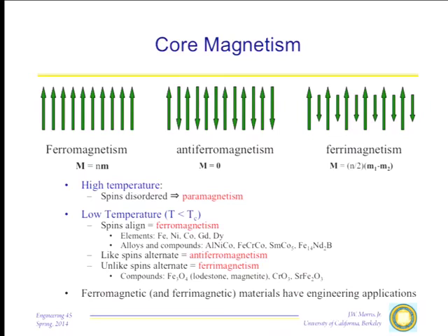It's also the case, when we get to more complicated materials, that there are a number of compounds that become ferromagnetic, even though the elements are not. Gosh, if you were a bit older, you would have used tape for recording music, and the best tape was chromium oxide. Chromium is antiferromagnetic, not a very good recording medium. Chromium oxide is ferromagnetic and becomes a good recording medium. There are quite a few materials in this ferrimagnetic case, Fe3O4 is an example, that have the nice advantage that they are oxides. And as oxides, they are simultaneously ferromagnets and electrical insulators.